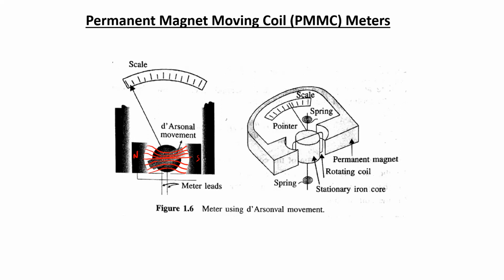And throughout the entire range of deflection, the torque is supposed to remain almost uniform. So a uniform scale can be used in terms of measuring a particular quantity.